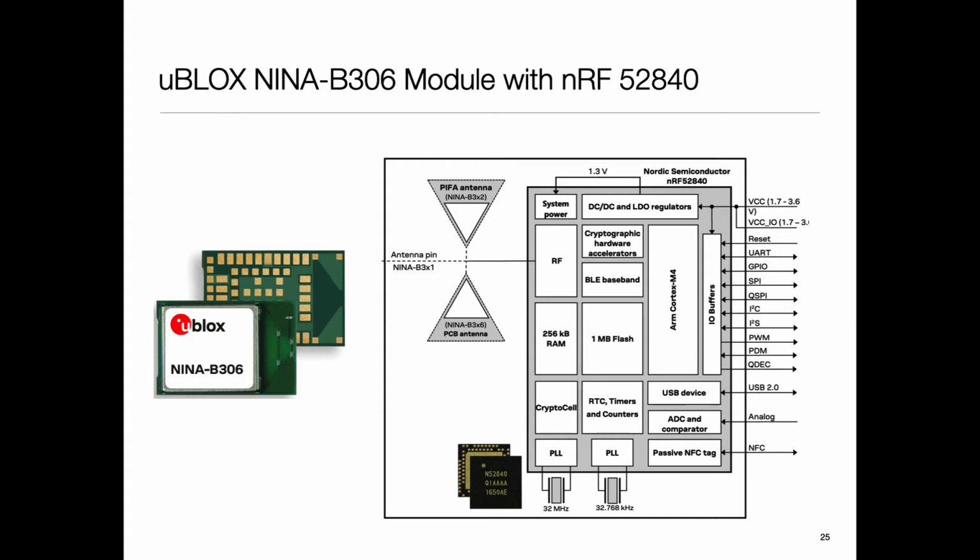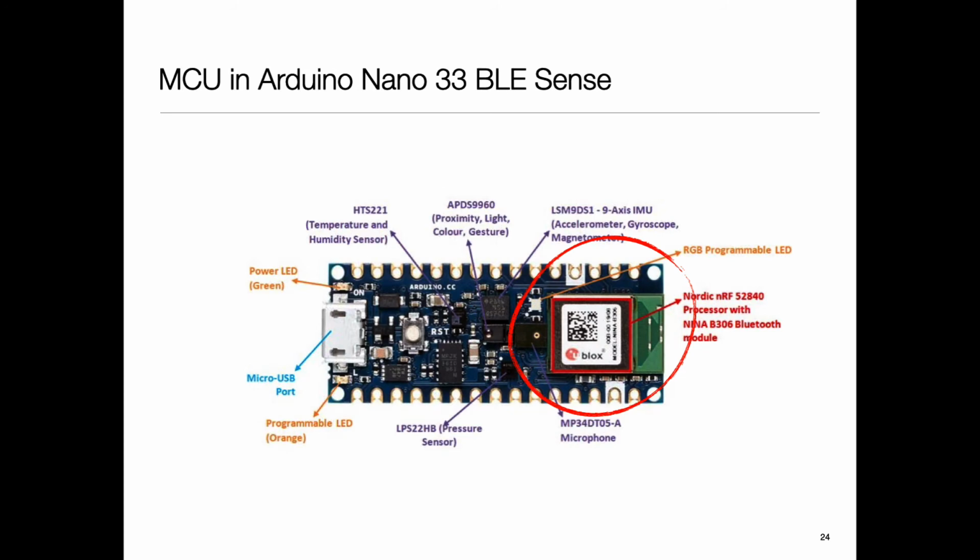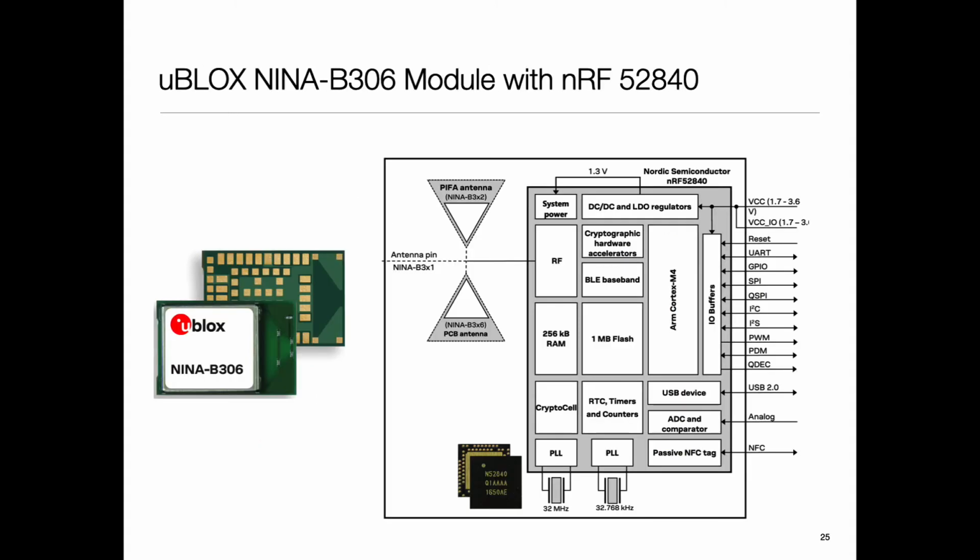So this device that you are seeing, the processor part, the microcontroller part, is really that tiny little thing from a different company, and it has integrated antennas. The rest of the stuff is really power, USB, and sensing support. It's a very common way of doing things.